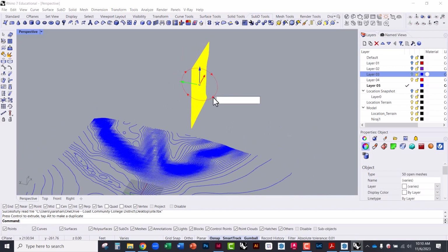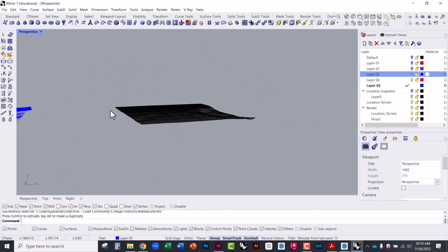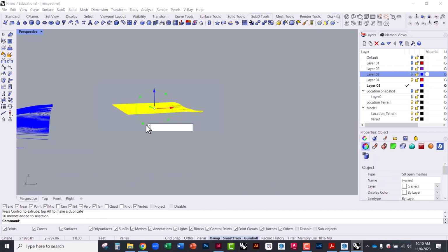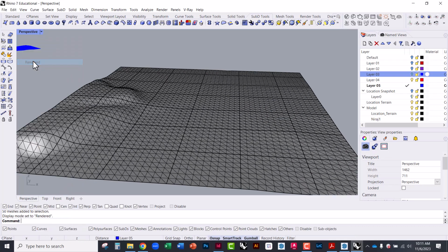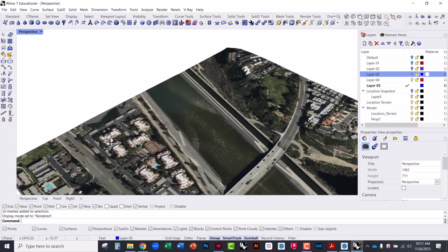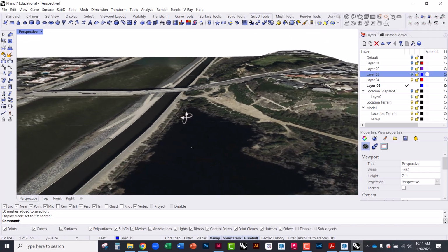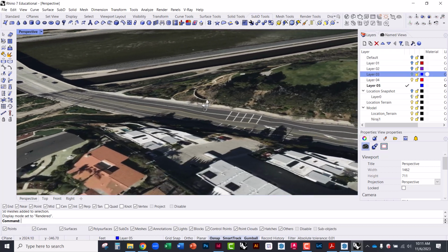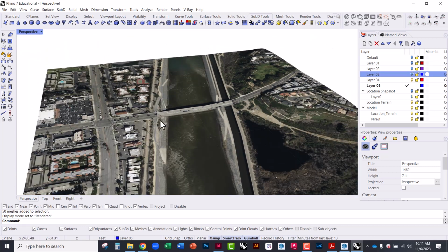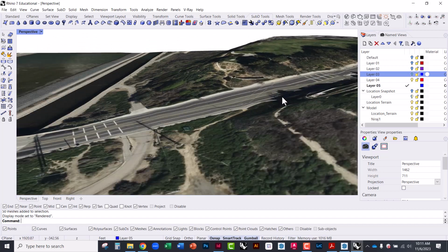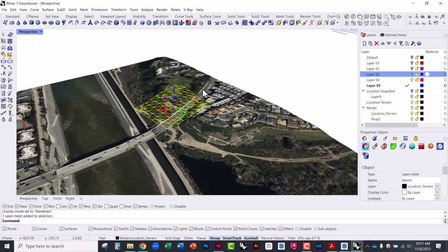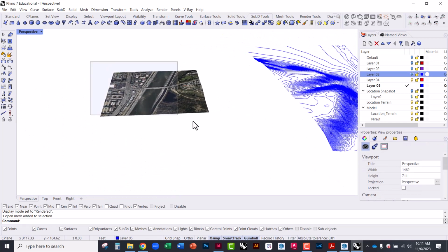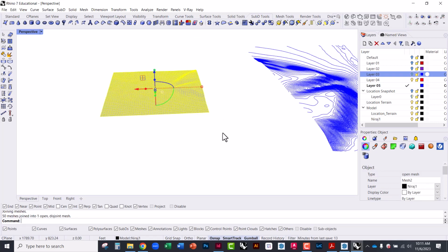So I'm going to rotate that -90. That's upside down. So I'm going to rotate this 180 using the gumball. And let's turn on rendered view, and that looks like it's mapped correctly. So importing it as an FBX would be the way to go when you're importing into Rhino and you want to maintain the texture. FBX does a good job of that. All right, so everything else applies. So I would select this whole mesh, join.